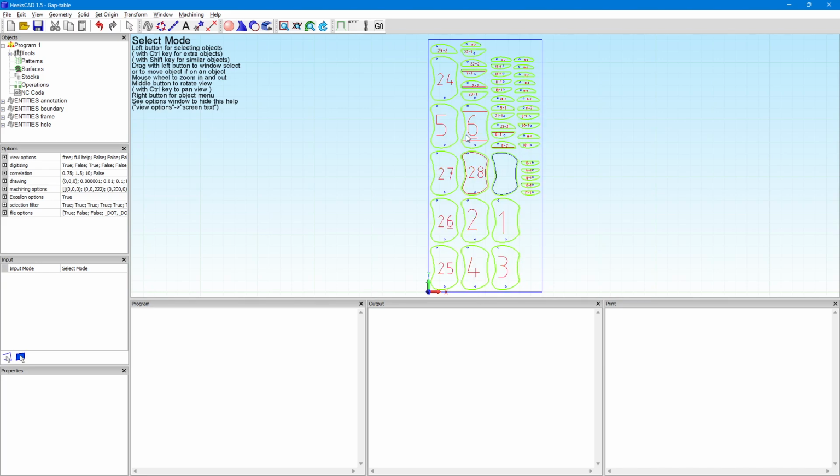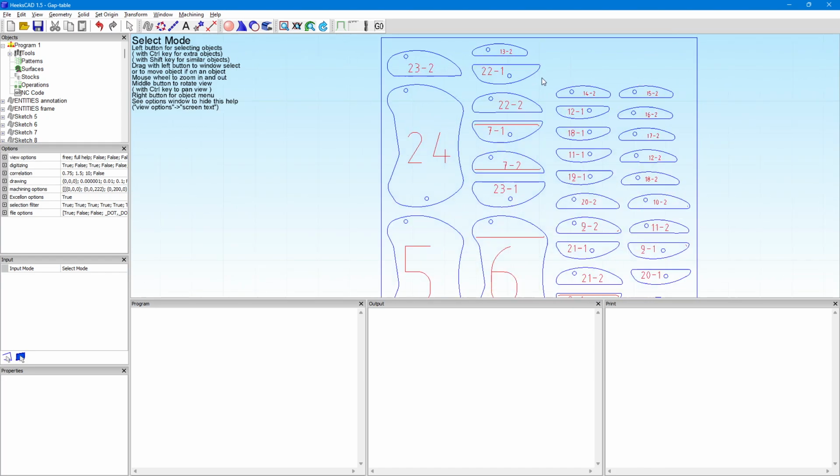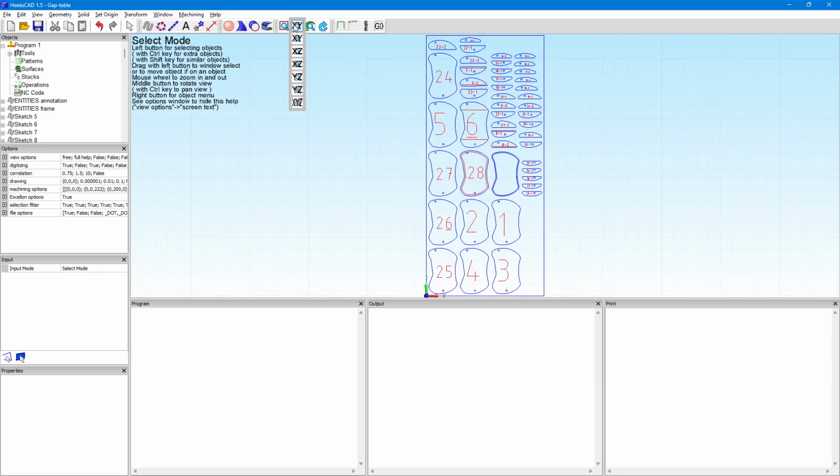First thing first is all the geometries are connected, so I want to select, right click and split the sketches, so all the sketches now became individual. Still circle have not, so right click the circle entity, split sketch, so now circles have become individual. Okay, only one thing that I need to make sure that I want to do.